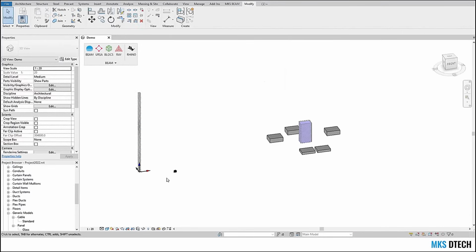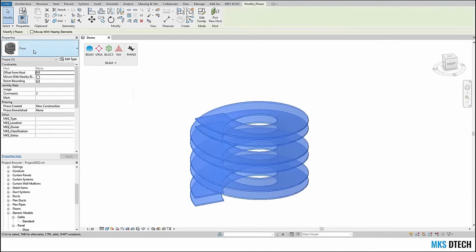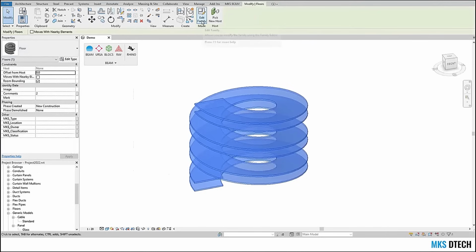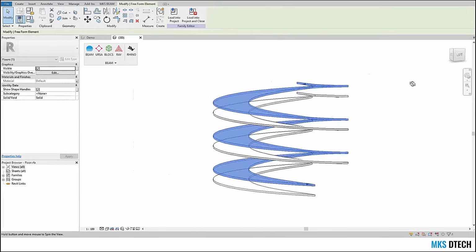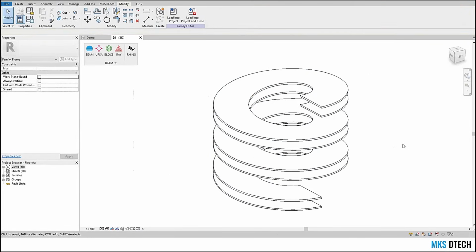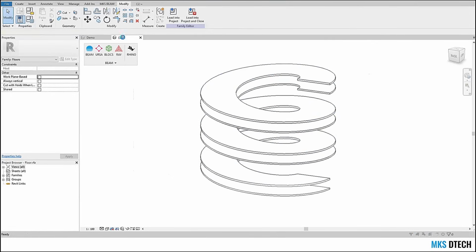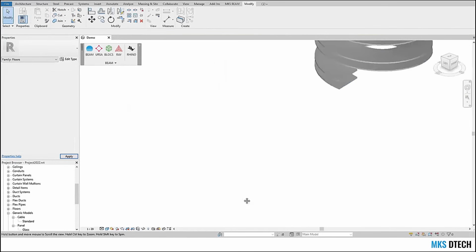But okay, let's have a look at our import. So we can see that this is a floor category, but, and this is something that we are doing only in BIM, I guess, we were able to import this floor as a loadable family. Let's go into the family, and we can see that this is a pretty good piece of geometry. We can still edit it. We can cut voids. We can stretch it a little bit more. We can edit until a certain degree. But now is the time for the panels.